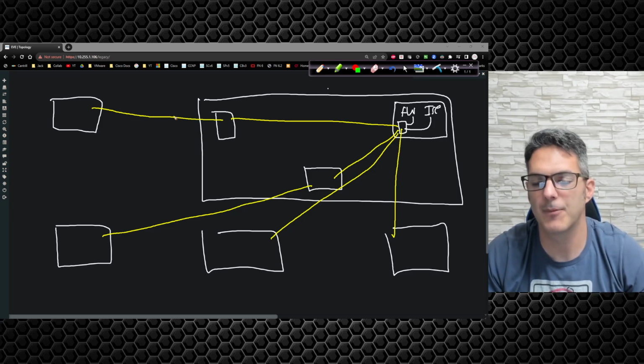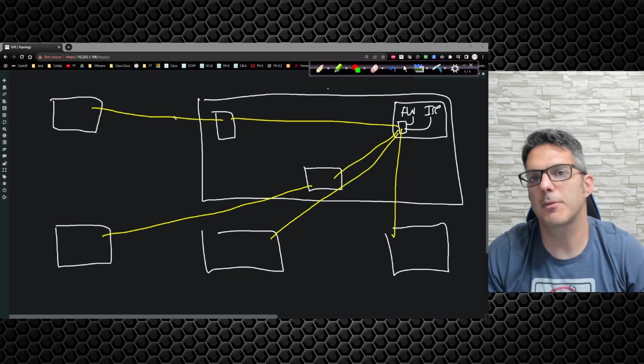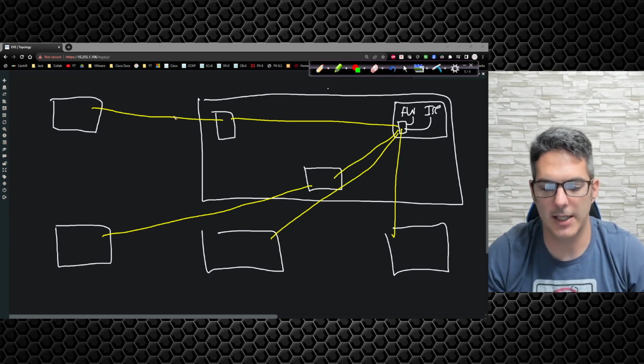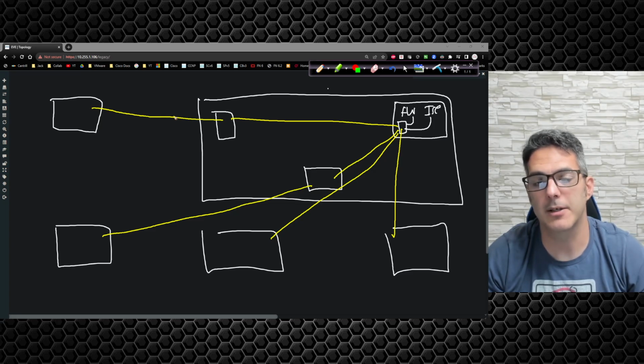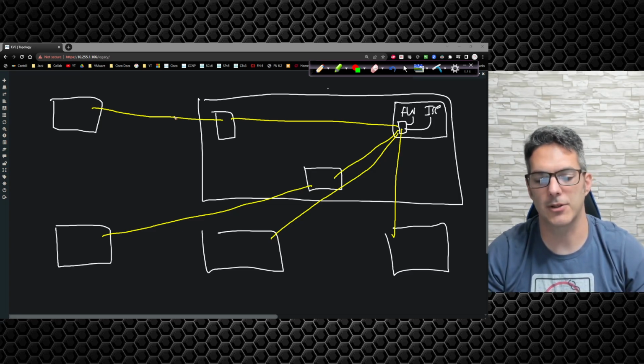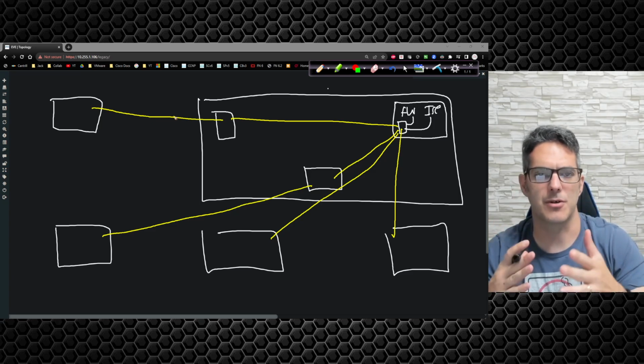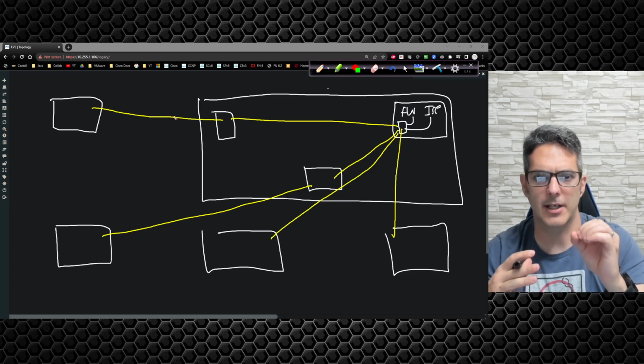Plenum. So when you are dealing with plenum spaces, there are a couple things that you have to keep in the back of your mind, and that is fire rating. Especially when you're dealing with copper, there is plenum rated and non-plenum rated. Plenum rated typically means that there is going to be additional insulation inside the actual Ethernet cable itself.